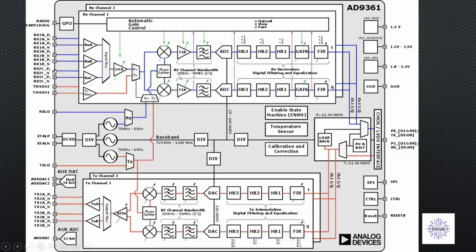We just need to apply a low pass filter after it, right? How can we do this? After reading the ADC information after the multiplier, we apply a low pass filter and then extract the DC values, which were SI_LP and SQ_LP, and use those to extract the amplitude AM and phi of the signal, right?